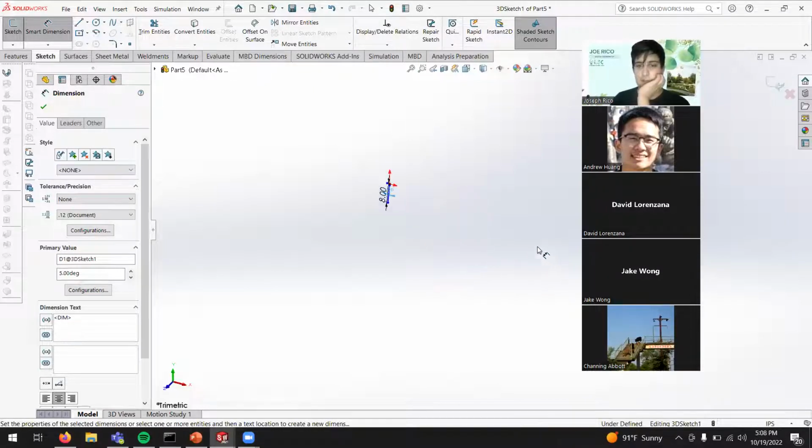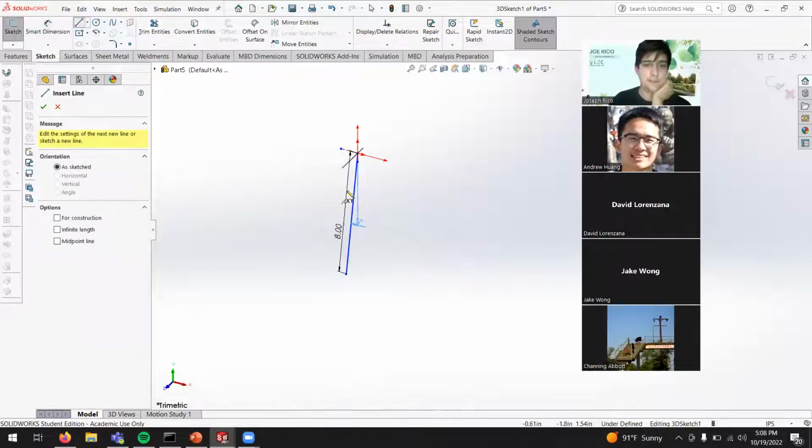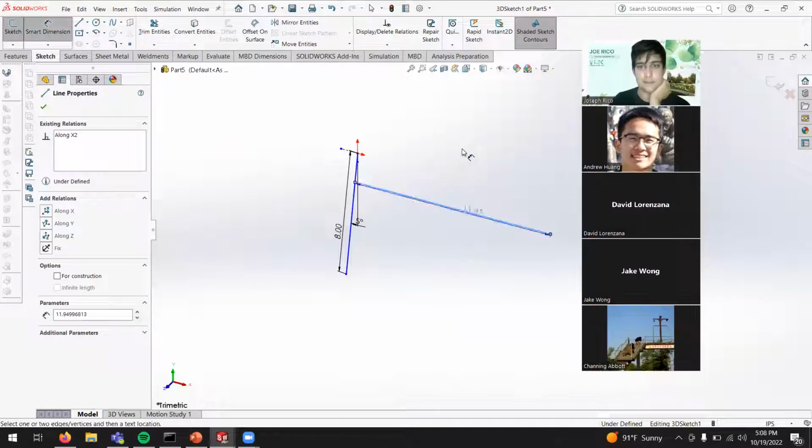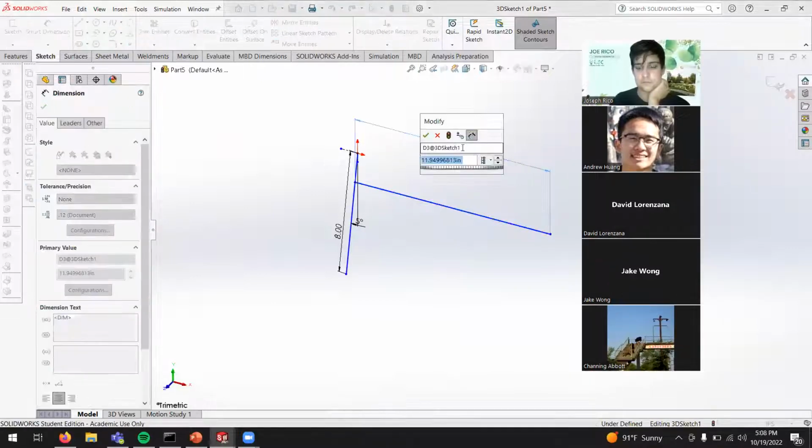Alrighty. Next up is going to be the top tube. We want the top tube to be on the same plane. And notice I'm not putting it on the very end because the center of the tube is around the line. So if I were to do the center, it would kind of sit on top of the head tube halfway, whereas if I put it inwards, it's not. Just like that. Get it started, and we will give this one a length of 4 feet.